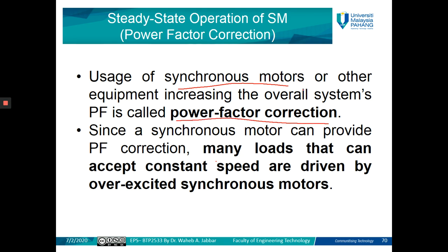That means we are going to connect some synchronous motors to the grid, and these synchronous motors will provide reactive power, which will feed the reactive loads that require reactive power, like motors, transformers, induction motors, and so on. So it will decrease the loss in the system, and it will also improve the overall voltage of the system.